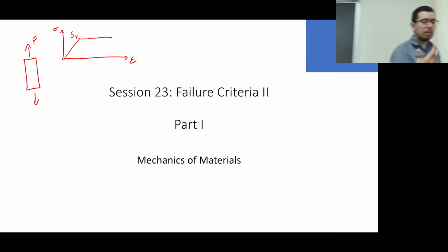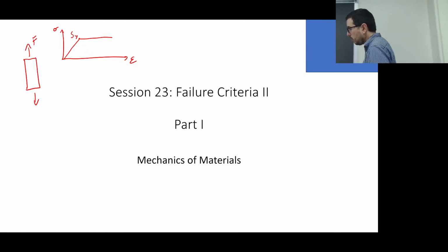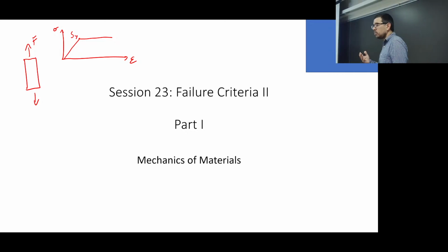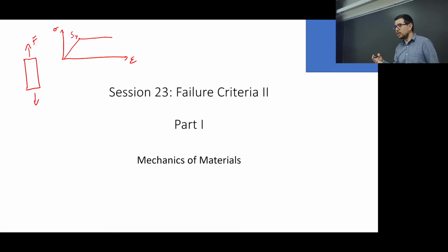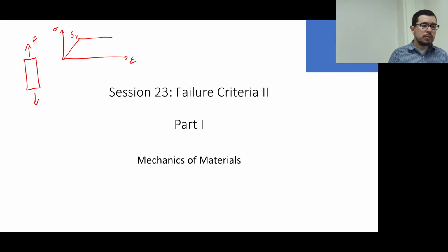But typically, when we're looking at systems with our metals or our ceramics, we're interested in thinking about what the yield strength is. Now, in the brittle materials, the ceramics, that yield strength is often really just the ultimate tensile strength because they fail catastrophically, right? And so there's not really this nice transition into plasticity. It's just bang.